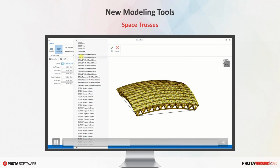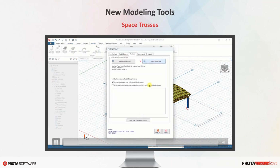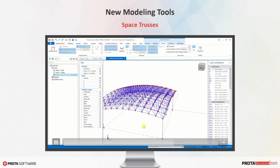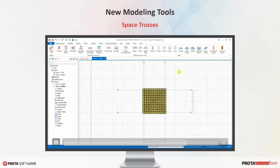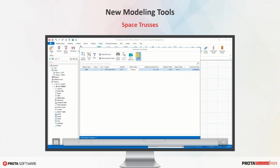With this macro, you can specify a region and insert a space truss geometrically. You can control parameters such as cell size, number of rows and columns, curvature, and more. We also have to enhance existing features around recently introduced ones. So, for example, you can extend an existing column to a selected space truss so that it becomes very easy to place the intermediate supports after space truss insertion. There is a dedicated design interface where you can check the sub-members and control the whole process in a well-coordinated environment.